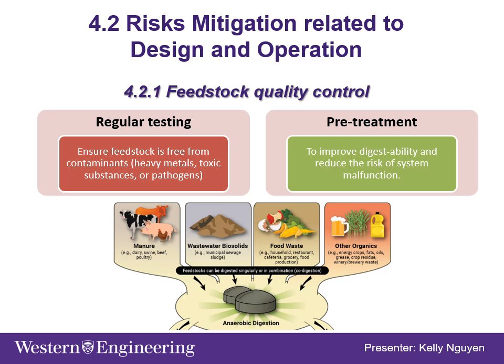And third, it helps us to decide whether the feedstock material is acceptable to proceed in the AD system or not. If necessary, the feedstock must undergo pretreatment using mechanical, thermal, or chemical methods to eliminate contaminants and pathogens. Pretreatment also makes the organic matter more accessible to anaerobic microbes, improves digestibility, and enhances biogas production and overall system stability.